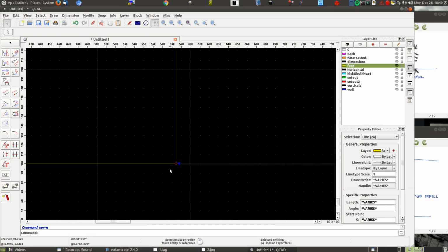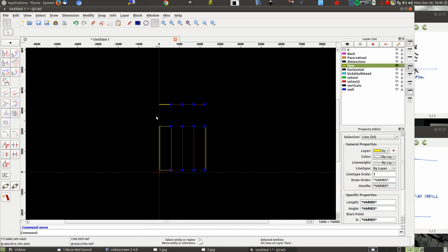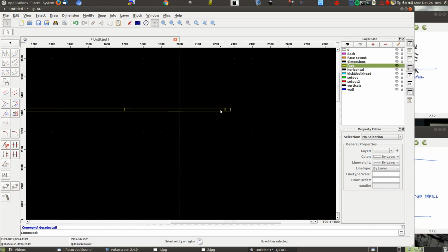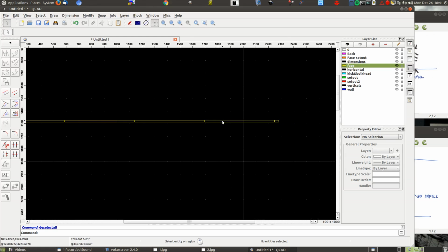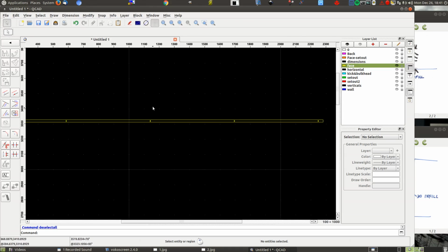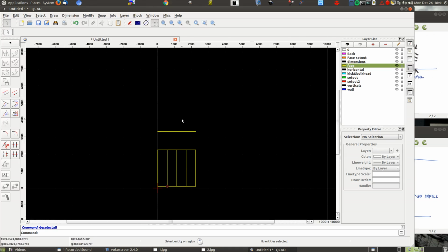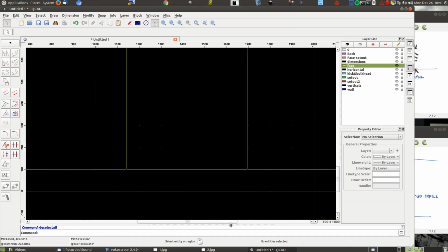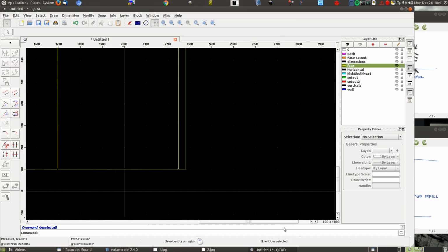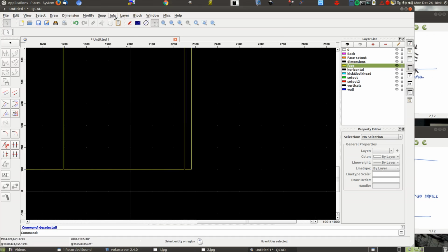Okay. Now because we had selected the top view, or plan view, as well as the front elevation, we've got all those doors copied. Now I'll go TN to select none. If we zoom in, we should have all our clearances perfectly drawn in. All looks good. Okay, so the same will be true for the doors here. So sliding back and forwards, you can see everything should be a 3mm clearance. And if there's any cumulative error, it would show up here.